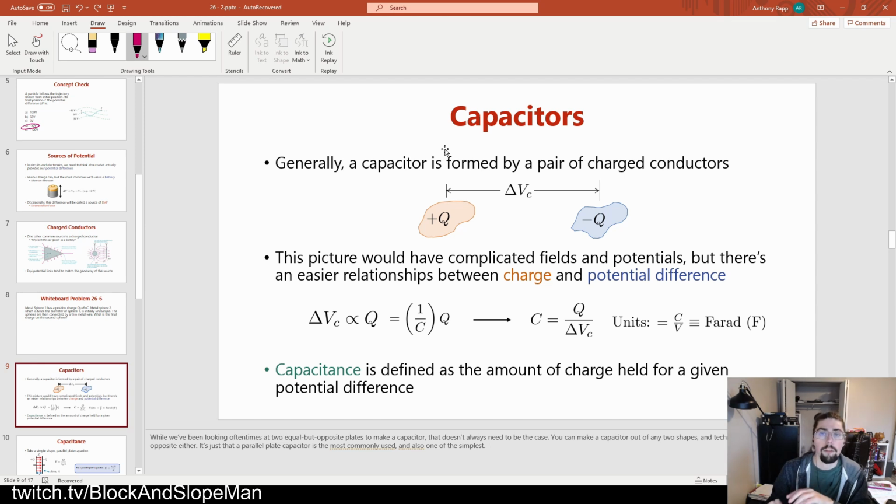So expect a lot of these things, picofarads and nanofarads. We're going to be expecting a lot of those values. You can get larger than that, and in fact, the largest ones that I've got in this box are something like this. It's a little bit larger as compared to the first one that we just saw. Oh, it's stuck in there now. They're all tangled together. But this is only 1,000 microfarads, right? So these things, to get up to a value like 2 farads, they do sell those, but they are as large as my arm. They're huge. To get up to single digits of farads, you need a massive capacitor.